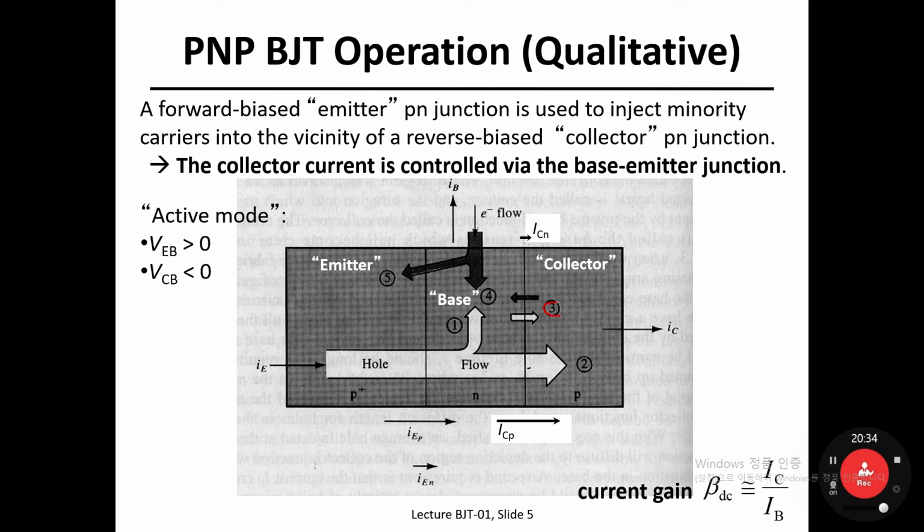Number 3, what is this? This guy and that guy. Number 3 is very simple. That is the very conventional and normal reverse bias current of what? The collector junction, right? So this collector junction has its own reverse biased current. Okay, so this number 3 current can build up the base current as well as the collector current.